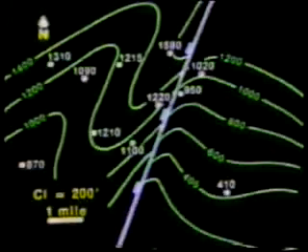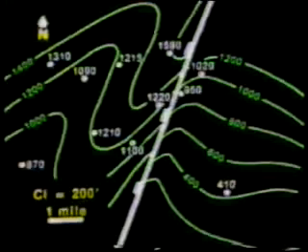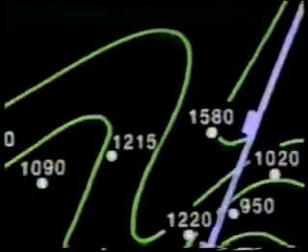In this case, contours should be developed independently from the east and west edges of the area, working toward the locality of erratic elevation. When this procedure is followed, the presence of a fault with a throw between 200 and 300 feet is indicated. A vertical fault, as depicted here, appears on structural contour maps as a linear trace which does not shift laterally with depth.